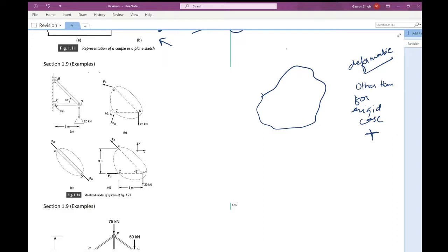For a deformable body, that has to happen, plus there is an additional condition for it to be called an equilibrium: every possible subsystem isolated out of the original system should have sets of forces which satisfy 1.5 and 1.6. Meaning, if you take a subset like this, this will also satisfy 1.5 and 1.6.